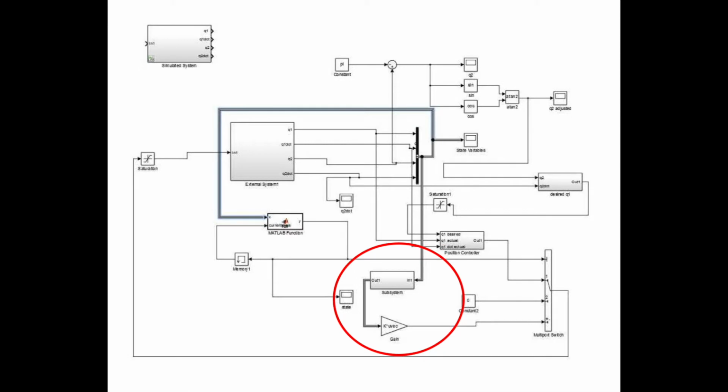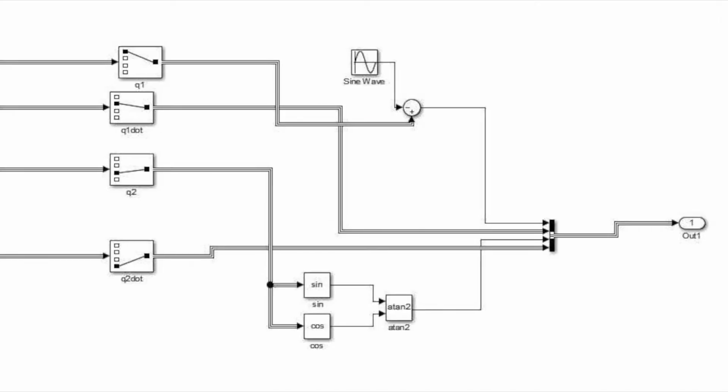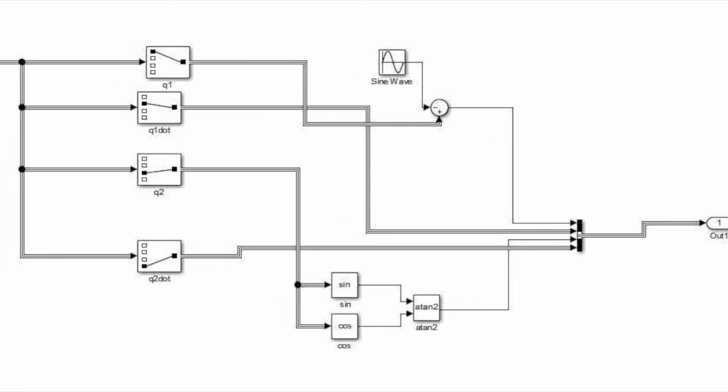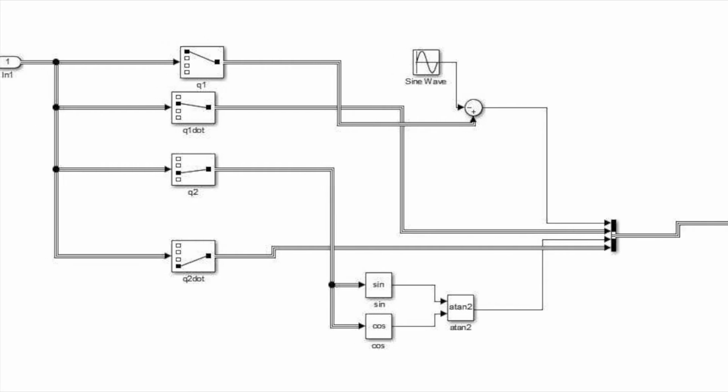In order to implement this into our system, the K matrix was then inserted into our Simulink by a gain block using the matrix multiplication, and the state variables were then inputted. After implementing this part into our state 3 controller, the system successfully balanced and matches our simulated system. After this, we worked on different types of position control when in state 3 using state feedback.